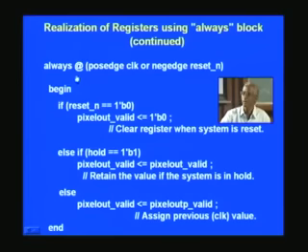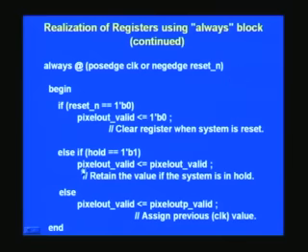And second thing is, you are not bogged down by so many details, I mean so many signals. If you don't stick to this, what I have observed over the years is a number of designers putting hundreds of variables in one always block, and the result will be chaos, and you will get drowned in the myriads of signals, so avoid that. You can always put any number of always blocks, and you can rest assured that each of these will be functioning concurrently. So there is no need to put everything together and then not make the system work, which will be a frustrating experience, especially for a beginner, and therefore even for a beginner this is highly recommended.